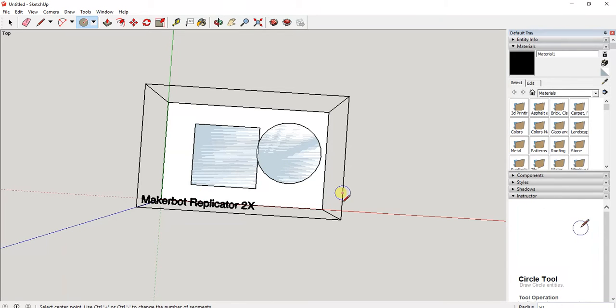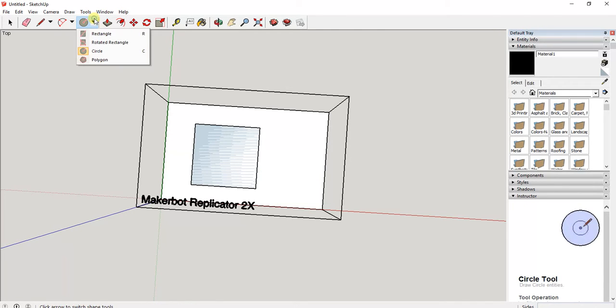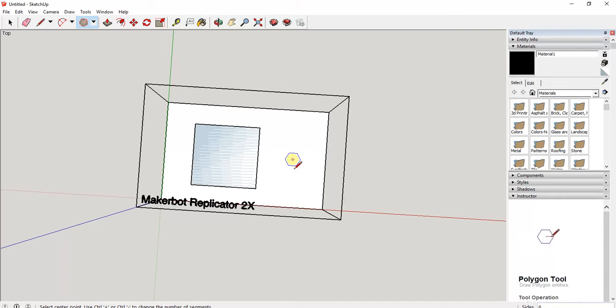All right, pretty easy. Now we can see that this is chopping and changing. Sorry, it's intersecting here, which is bad. We don't want that, so I'm going to undo because I'm going to stick with the square. And lastly, if anyone wants a polygon, well, we can do the same thing. It does the radius again. So a 50 radius will produce what we're after, which is a 10 centimeter, 100 millimeter diameter. All right, so that's our base. And again, I'm going to go with square. What I'm going to do next is get this select tool here, and I can select.